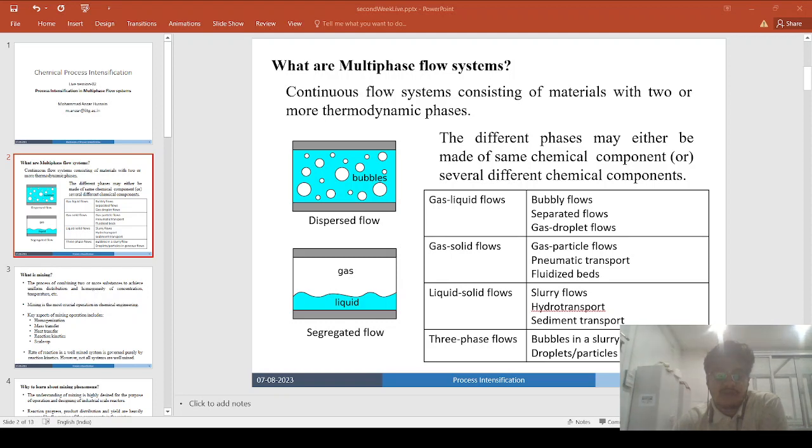The direct fluorination, as an example, serves as an inspiration for the development of flow distribution, allowing controlled scaling of the gas-liquid reaction from a few channels to a large number of channels with uniform flow distribution of a flow regime of plug or liquid segments. So these basically come under the intensification by flow in special geometry of the channel.